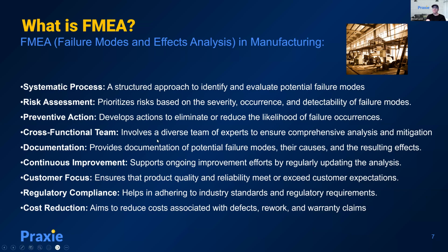It's a preventive action. It's designed to eliminate these kinds of failures. It's also great because it helps with cross-functional teams. It provides documentation of the process, and a framework for doing continuous improvement. It also focuses on the customer. A lot of the failure mode questions are really designed to address customer focus and the quality and reliability for the customers. It creates objective evidence and history for regulatory compliance, and should also, because it's eliminating risks and errors, reduce overall costs. So that's what failure mode analysis is.